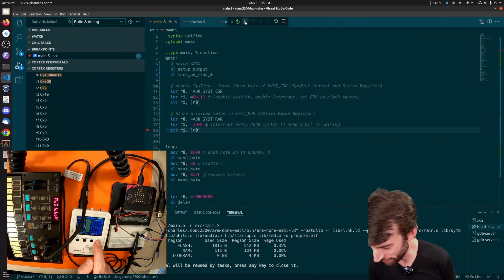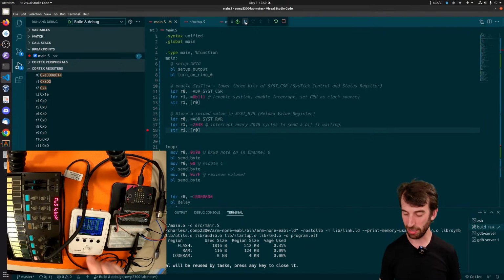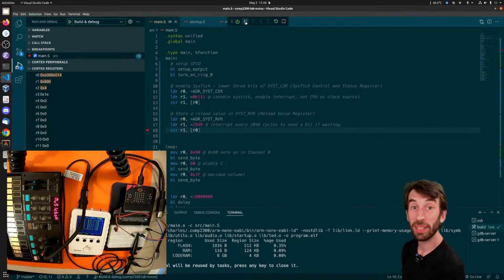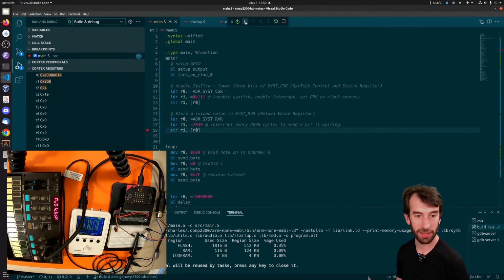It does it. Let's have a look on the scope. So there's my MIDI message going by, and it's actually 3 bytes all together really quickly. As soon as we finish 1 byte, my little byte sending program notices and sends the next. So the first was 9, 0.